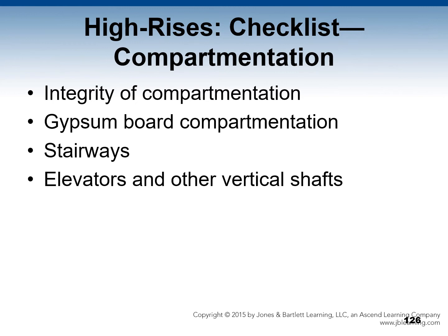With compartmentation, you have the integrity of compartmentation. Are there utility openings or underfloor openings such as for computer cables? Do barriers extend to the underside of the floor above? Do fire doors function properly? And again, all this is on your high-rise checklist.